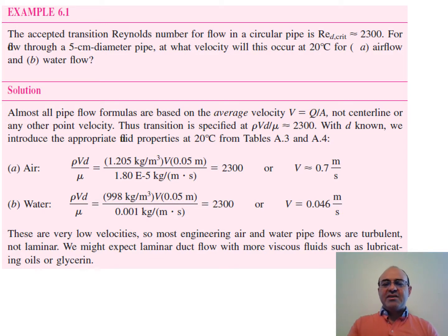In the previous chapter, we briefly discussed the fluid in a pipe, and we said that if Reynolds number based on the diameter of the pipe is less than 2100, then the flow is laminar. If it's larger than 4000, it is fully turbulent. And as a borderline, usually a Reynolds number of 2300 is considered as the borderline between laminar and turbulent, because usually there it is difficult to come up with or develop equations for the transition region. As a result, for practical purposes, the flow is either considered as laminar or turbulent.